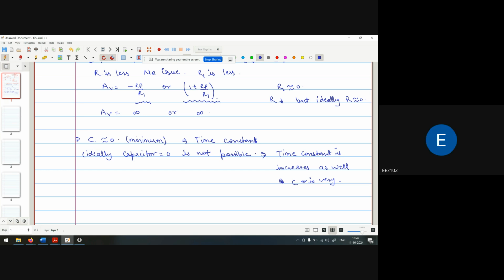In a single voltage source, if we are not using the capacitor, we require two batteries. One is for the input signal battery like V1, and the second is VDD by 2 that we connect at both terminals, inverting and non-inverting. So we require two batteries. To avoid this, I just use one capacitor as a battery.